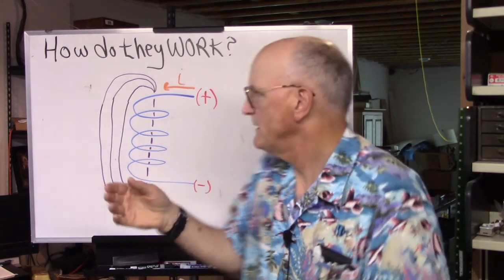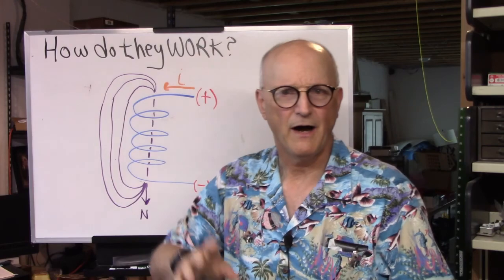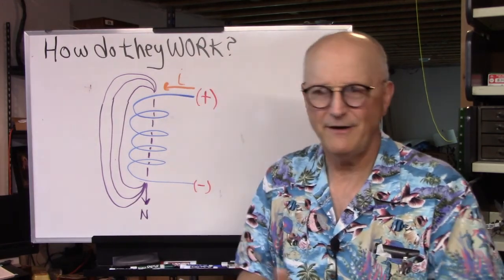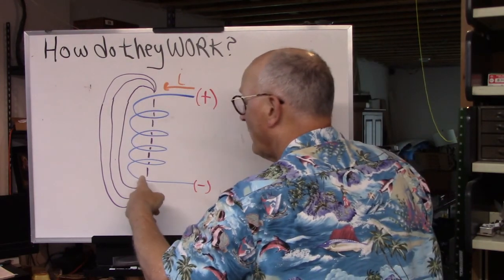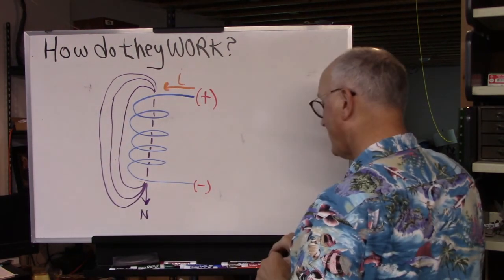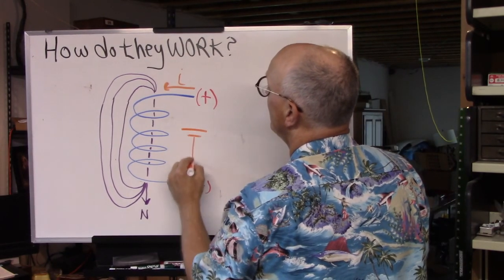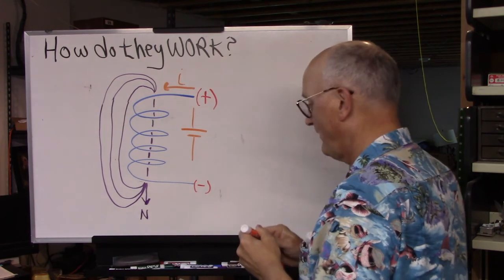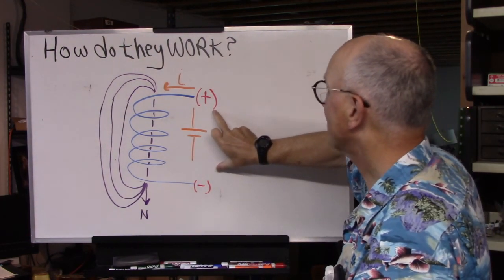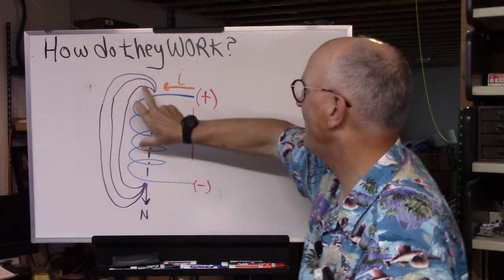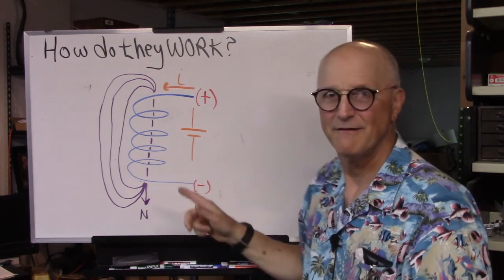All it knows is, hey, I have a magnetic field moving across me, I need to generate a potential difference. So as current goes down, the moving magnetic flux essentially creates its own battery to try to maintain the electric field across itself, so that the current doesn't change, so that the magnetic flux doesn't change.